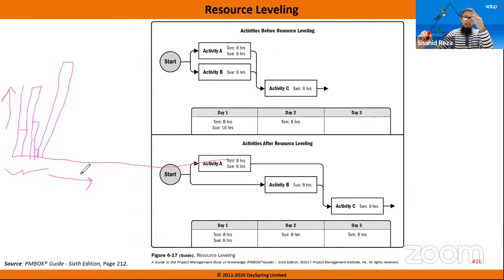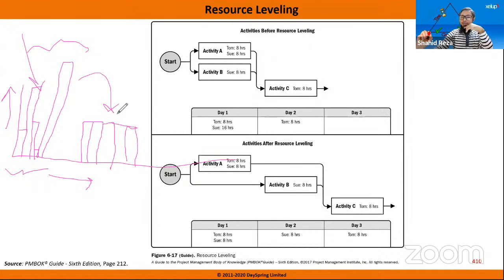So what you have to plan is smoothing here. Here you have to use resource leveling. You have to plan like this: say for 5 weeks, my resource will be like this. There should be leveling, so that I can easily find laborers. Otherwise, if you use the earlier plan, you will fall into trouble, because you will not always get the correct or appropriate laborers for your task, for your job. So this is also another perspective of resource leveling.